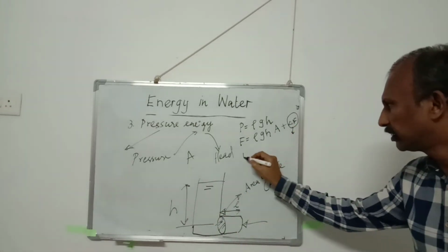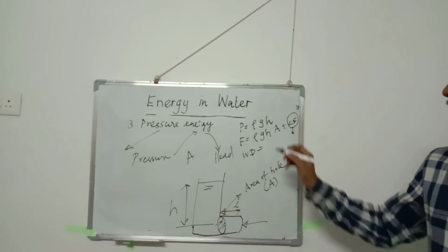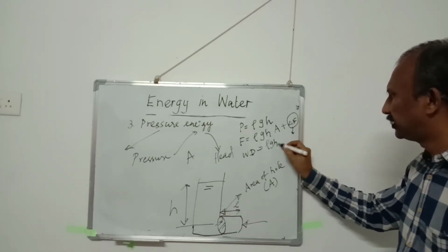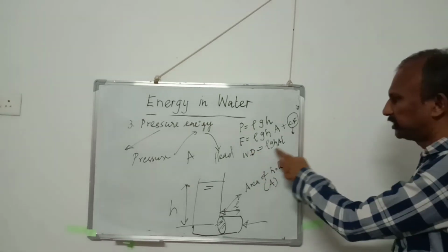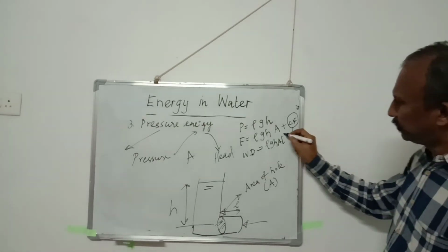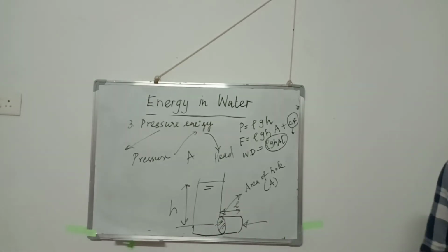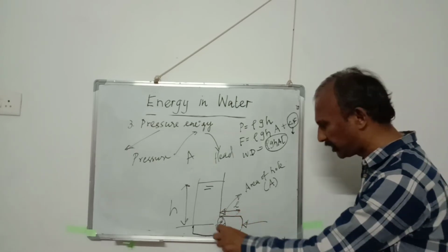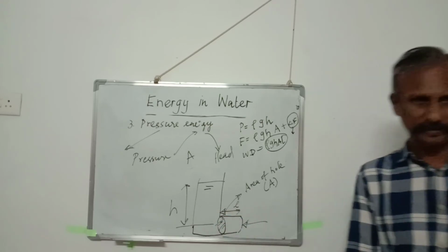So what is the work done to push this water particle inside? That is equal to force into distance. Again, rho g h A L. So work done is rho g h A L. So we have done work of this much to insert into the tank. So what has happened? Our work has got transferred into pressure energy for this water particle, and that pressure energy is stored inside this water.